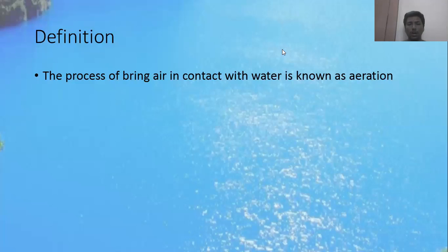Okay, you need to adopt some unit process or unit operation. Unit process means changes in the quality or the characteristics of the water done by adding some chemicals, or maybe through any biological aid, either for water or wastewater treatment. We call it a unit process. Unit operation means the water is subjected to the action of physical forces which tend to change the quality or the characteristics of the water. We call it unit operations.